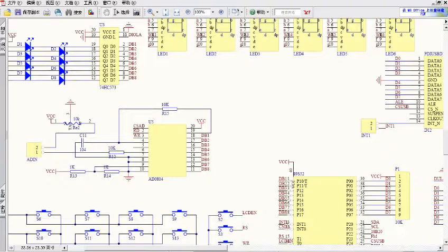You can see the second leg of this latch is DB1, and the first leg of the microcontroller has been named DB1 as well. Which means electrically those two legs are connected to each other. This is different from our normal electrical schematics.